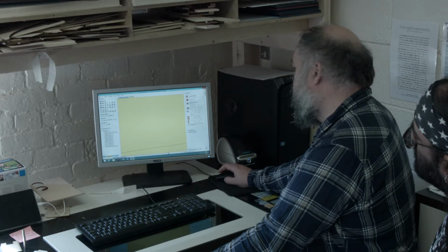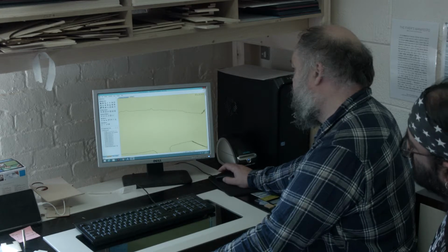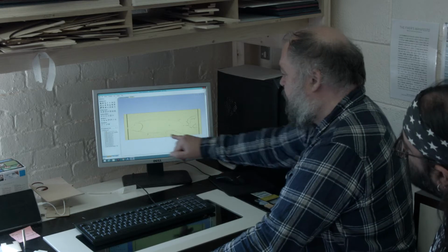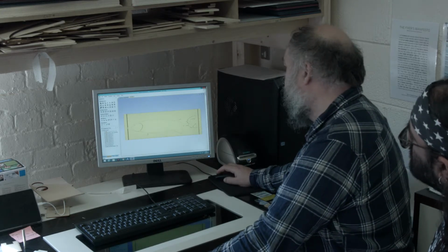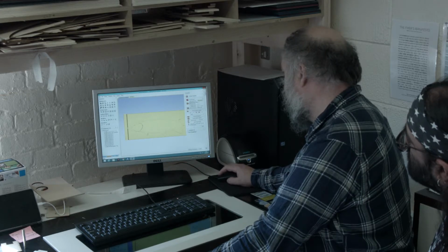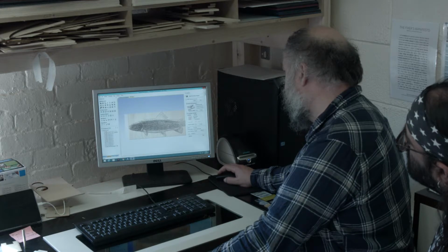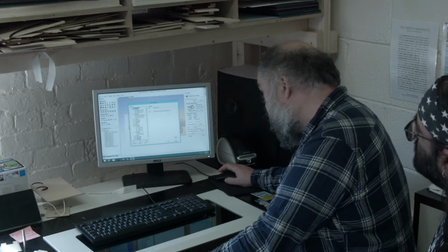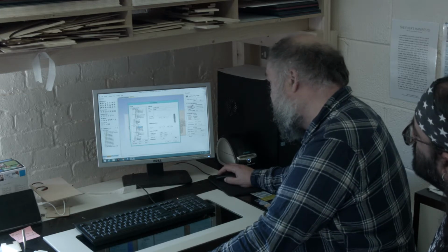It's a preview all tool paths. You can see it's only just taken the levels from there. I can then go in and do the smooth tool path. And what I'm going to use here is a much smaller tool. So I'm going to use a 2mm end mill.